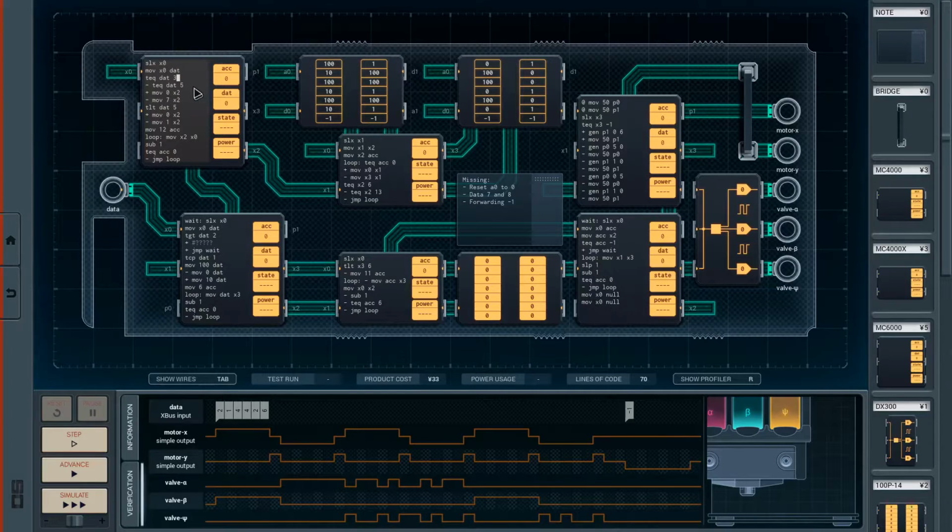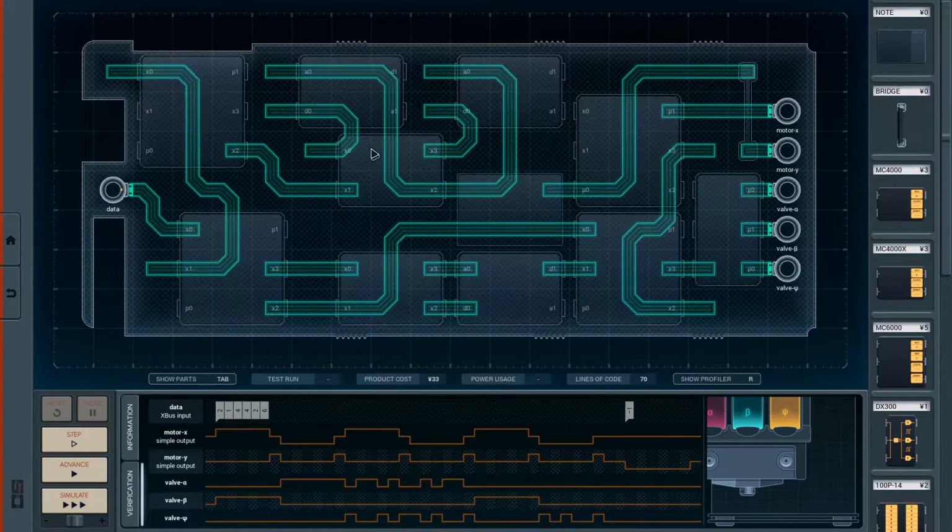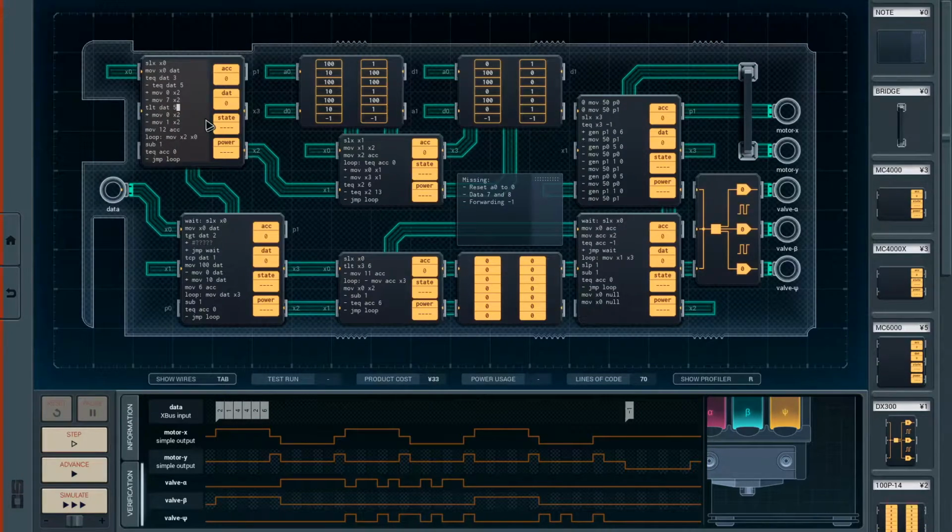So right, if it's a 3 or a 5, then I want my address to be 0, otherwise I want it to be 7. So that selects the column, and again, these address lines are wired together, so I select the address in both at once. Then if it's a 5, I guess I want this if it's a 5, and this if it's something else. Oh no, if it's 3 or 4, if it's less than 5. So if it's 3 or 4, I do this one, with whichever column I selected. And if it's 5 or 6, I want this one. So yeah, there's a bank selector controller.